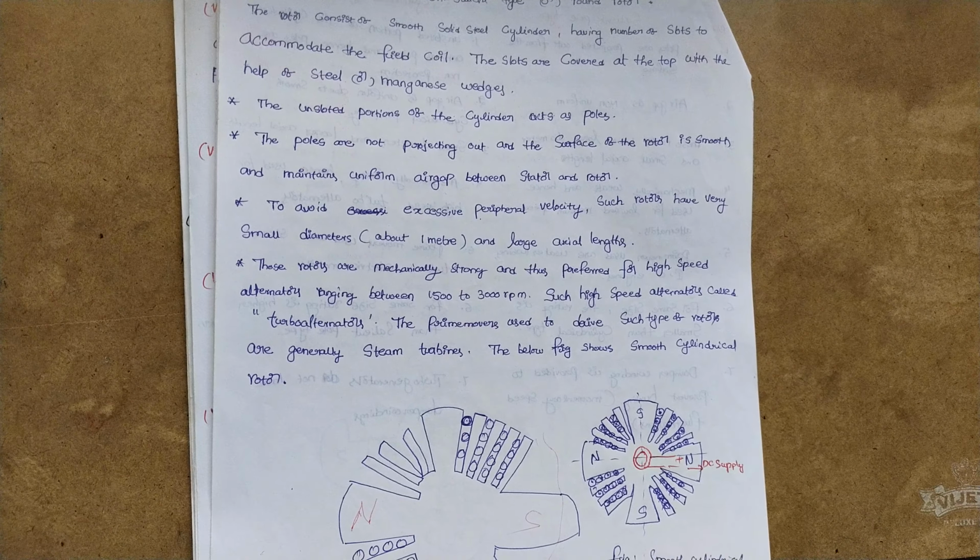Coil: when two or more turns are grouped together, it forms a coil. A coil may consist of many turns; the number of turns are wound on one coil. Coil side: what is coil side? A coil consists of many turns. The part of the coil inserted in a slot is called the coil side. In each slot, one coil side will be there.